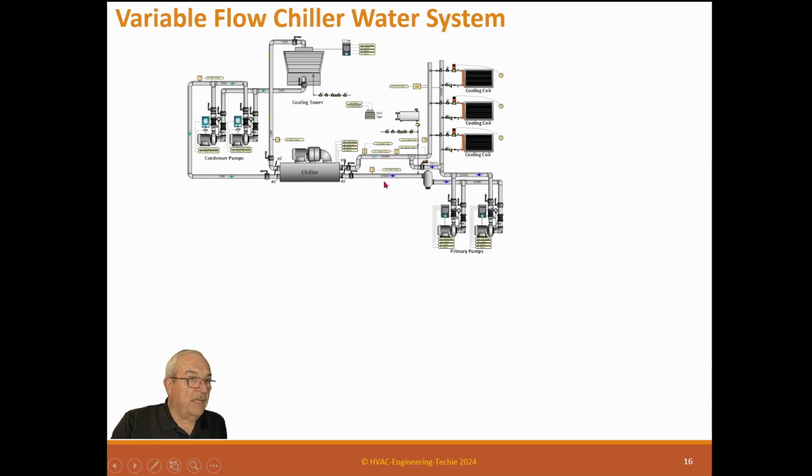My take is always put a flow meter in here. They're cheap nowadays. Put a flow meter in that pipe, and this valve will run to that flow meter exactly. Really slow, really good, really strong set point, won't be off, and you won't have to worry about it, for the price of a flow meter. And this differential pressure will drive you to headaches forever. Do a flow meter. It's the way to do it.